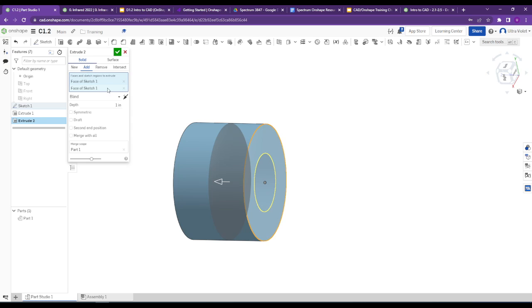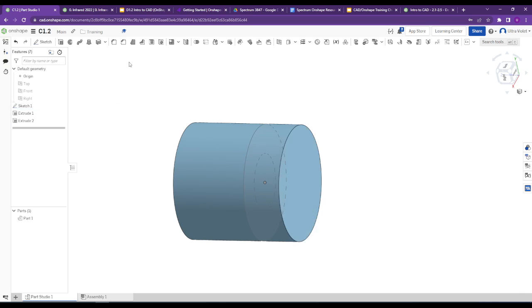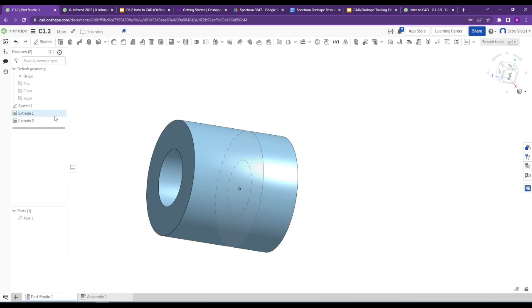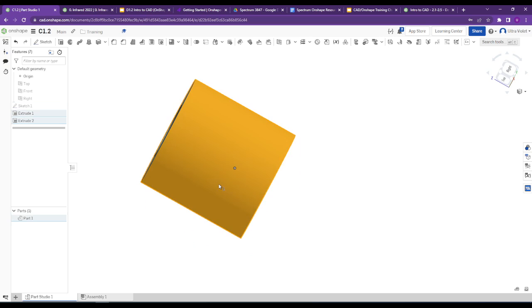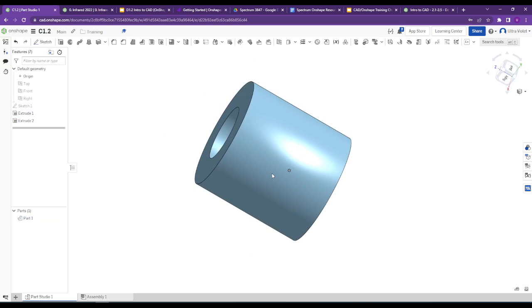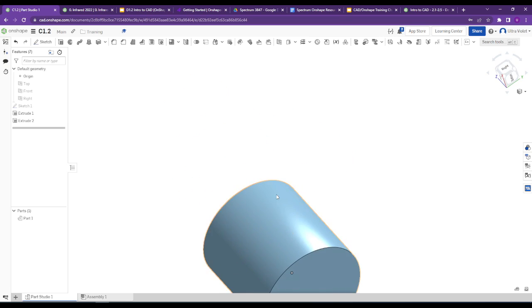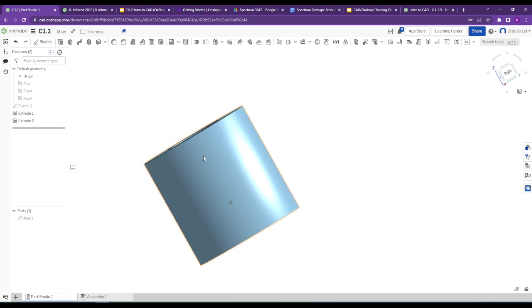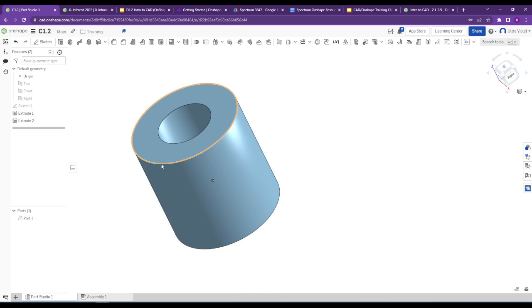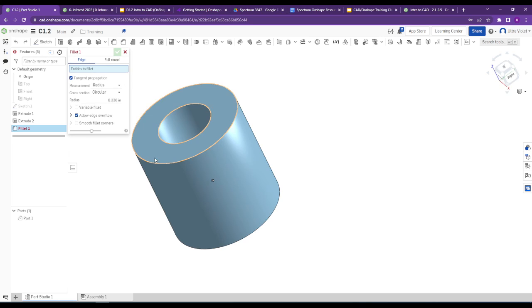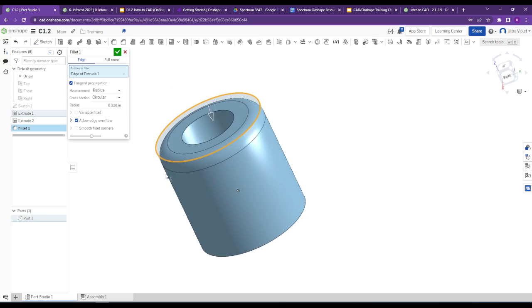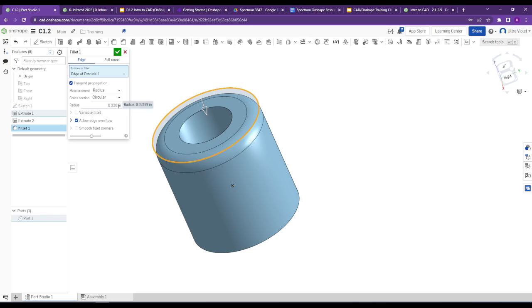So if I add, let's see, so yeah, I can add this in. And so now we have this like little bottom section there. I can now hide the sketch. And this whole thing is just one complete part now, because each feature just adds to that part. So you can go even further. You can make little details. So say we don't want these like sharp edges. We can fillet them, which is to like round the edge. So maybe I want to round this outside edge, make it less sharp. You can set the exact dimension of how you want to round it, maybe like 1/4.